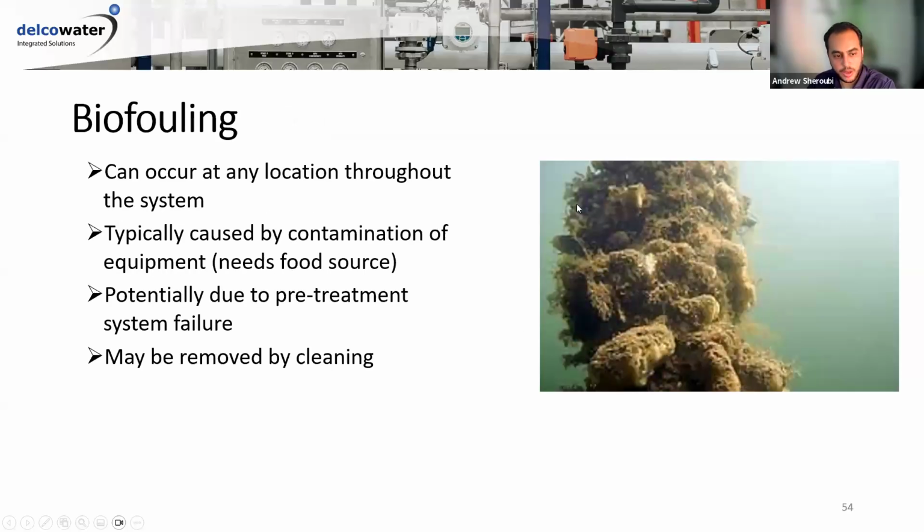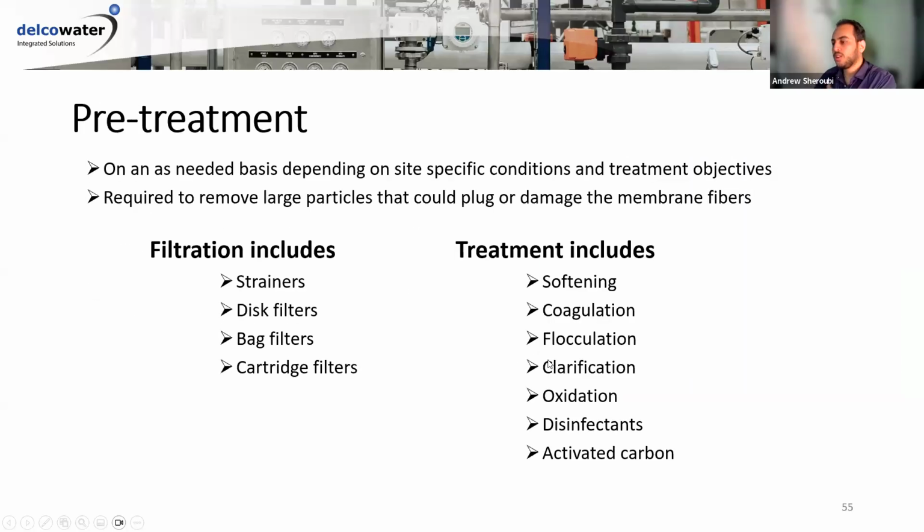And biofouling is obviously still a concern. This is the same slide as I had before. So what we've done before is the UF is more robust than an RO. So we've put a UF membrane first for surface water applications that removes the turbidity, the suspended solids, and all that stuff. And then we put an RO or an NF membrane after to remove the dissolved compounds.